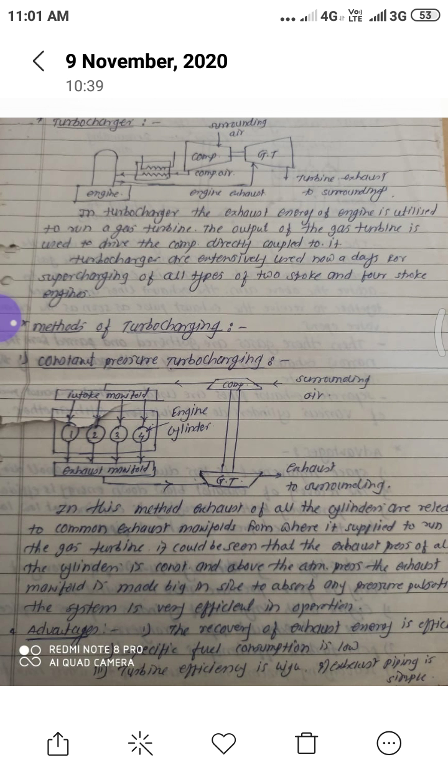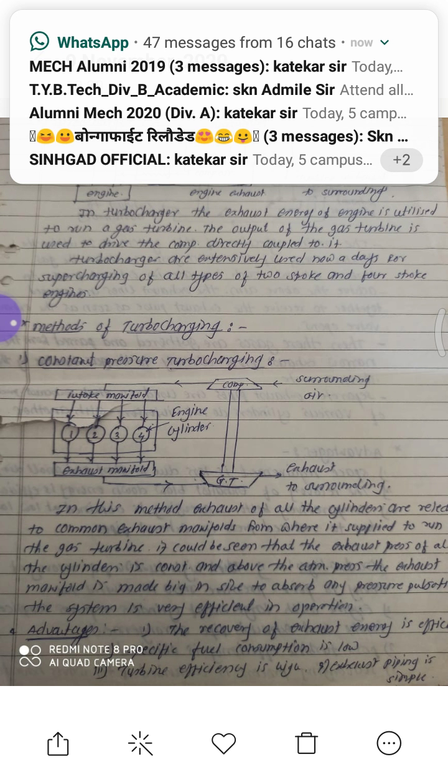So this is nothing but what? Turbocharger. In a turbocharger, exhaust gas energy of the engine is expanded over the gas turbine. The gas turbine produces some amount of output work, that is rotary motion, and that rotary motion of the gas turbine drives the compressor.